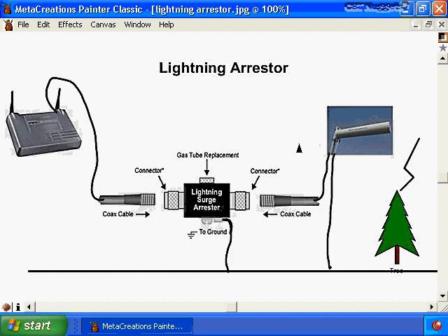However, it's best practice to place the lightning arrestor as the very, very last component on the line, so to speak. You want to have this just before the antenna, and you want to place your RF attenuators or RF amplifiers and power over Ethernet devices and all that kind of stuff behind the lightning arrestor. So by doing that, you'll hopefully be able to protect your RF amplifier and attenuator, etc., your bridge, your access point, whatever the case may be, from these surges in electricity. So you want to place this right here as the very last part in your chain before the antenna.